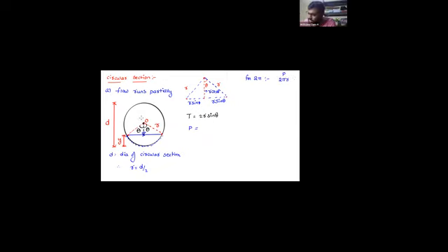Okay. Now what is the angle made by this sector? For angle 2 theta, it is 2 theta into r. For the total angle of 2 pi, the perimeter is 2 pi r. For the angle made by this sector, 2 theta, what is the wetted perimeter? 2 r theta, or 2 theta r. So I can write it as 2 r theta.